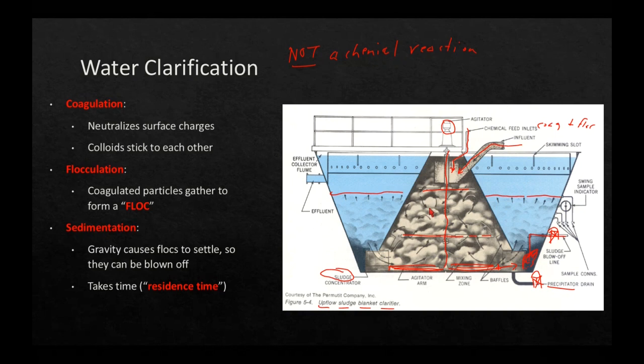So water comes in, we add the coagulant, we start to see very tiny flocks forming, and then form larger spongy flocks like we saw in that diagram. And then before you know it, we've got this really dense sludge down here on the bottom.